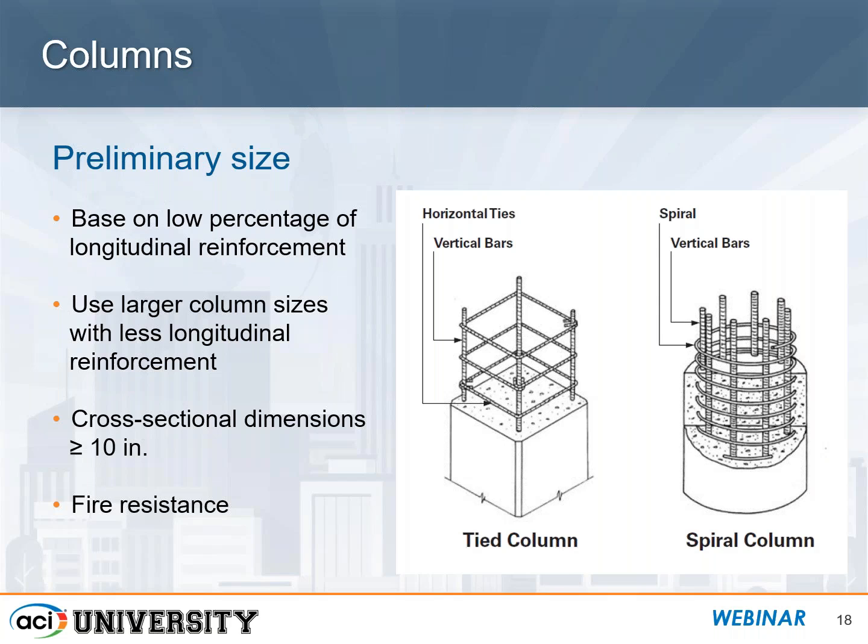And I don't think anyone would use something that small, even for relatively very small loads. Having something less than 10 inches, you can imagine, even providing ties in something like that is going to be challenging. So from an overall constructability perspective, 10 inches is the bare minimum. We would certainly recommend 12 inches or above in order to come up with a constructible construction of those columns.